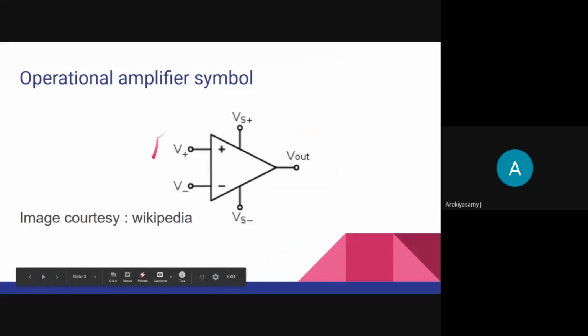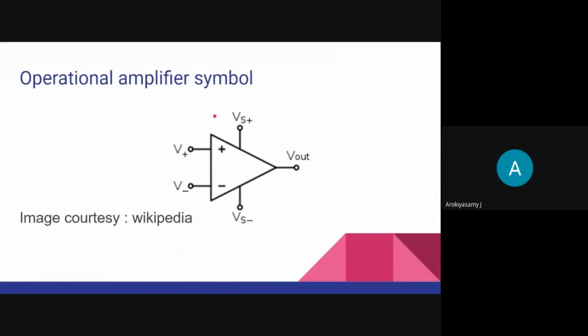An operational amplifier is an integrated circuit amplifier, and it has a double-ended input. There are two inputs, because in other amplifiers there will be only one input. But here there is one pair of inputs, that means two inputs: double-ended input, single-ended output. Usually it is a single-ended output. Double-ended output is also available in some amplifiers, but here it is only single-ended.